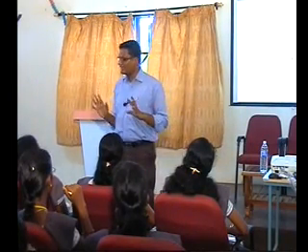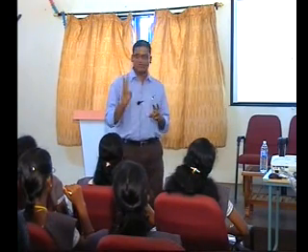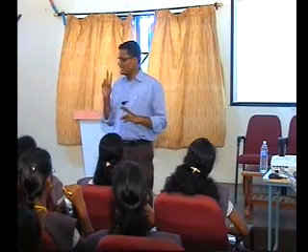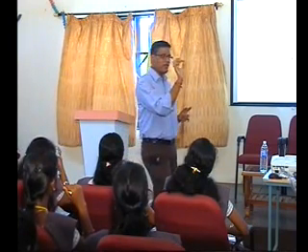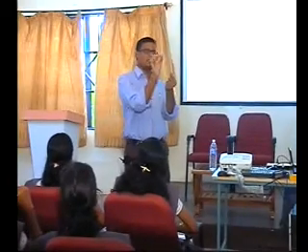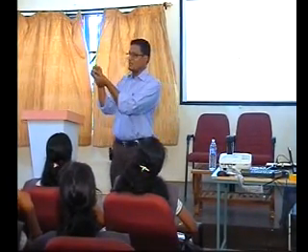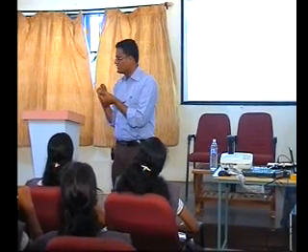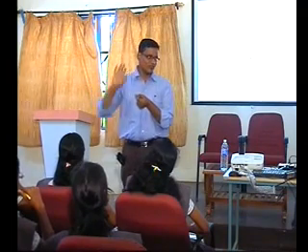This is generally speaking. Here we have two parts. Stuck at 0 part, stuck at 1 part. That means that particular point of the circuit is always maintained at 0, logic 0. That particular point of the circuit is always maintained at logic 1. So these two are called as stuck at 0 and stuck at 1 faults.